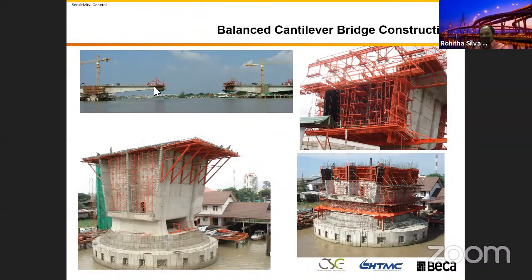This is one of the major problems when we have, in the middle, a reinforced concrete cast in situ section. We call it the stitch pour. That stitch pour, you have the gap like this. You can't build your bridge with a gap of 100 mm or 80 millimeter; 20, 30 is acceptable. And then to set that bridge element together is not that easy. We know from our experience, yes, we had those situations, and we rectified them.